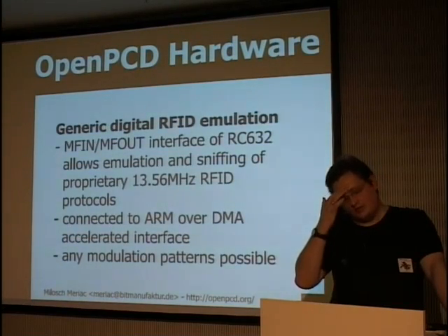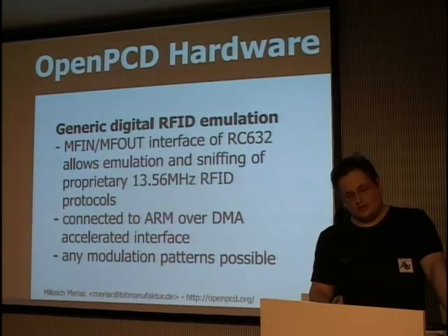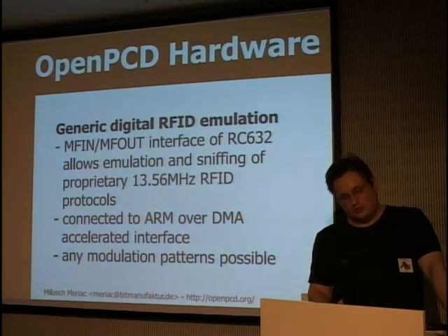And also this is the place you want to tap in if you want to support protocols that are not supported by the chip natively. There you have the same approach. You get the oscillator frequency, 13.56 megahertz. You use the timer input to derive the clock frequency you intend. You can adjust the phase, and you configure your DMA output to sample or transmit data that you can pre-calculate. So this makes emulation of protocols that are not supported very easy.